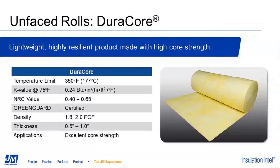So DuraCore has the same temperature limit of 350 degrees, a thermal value of 24, NRC values between 40 and 65. It is GreenGuard certified. Densities available in 1.8 or 2 pound, and in thicknesses from 1/2 inch to 1 inch. DuraCore also has the high post-consumer recycled content at 56%.